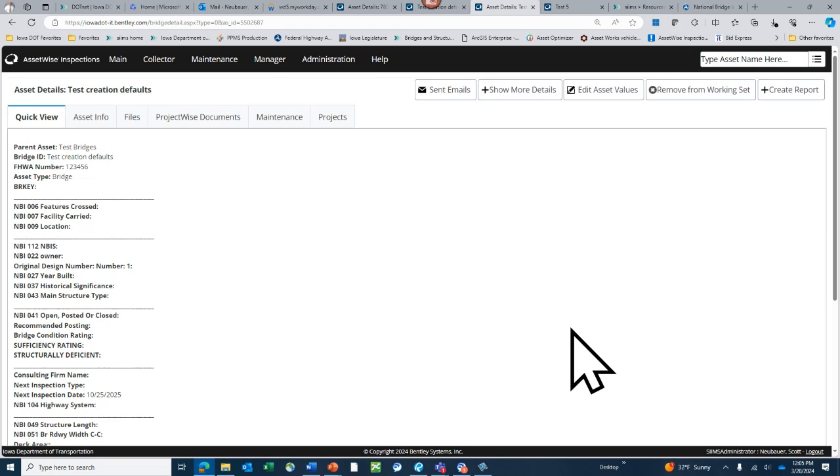If your timber deck is controlling, then you can say allowable stress. If it's the steel girders, you can say load factor. But you can say load factor and still have the timber deck control using allowable stress. So it's really not wrong either way. But if the timber deck is controlling, I'd put allowable stress in as the method.